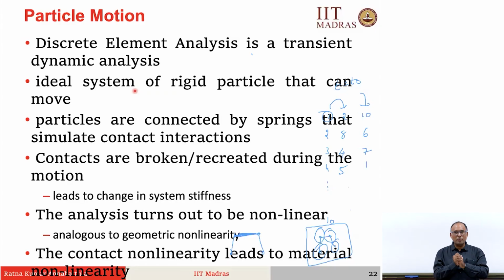If you are using the soft sphere model, you actually use the apparent overlap between the particles in order to compute the force acting on the particle, and that force is used to solve your Newton's second law of motion, and then get both linear and angular displacements and velocities and accelerations. So, that is the crux of your DEM simulation.